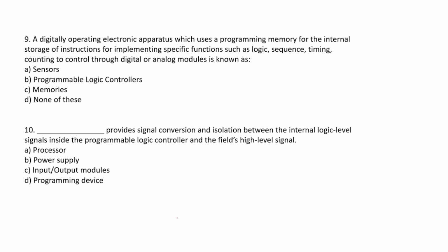In an electric joint drive system, it uses electrical motors to actuate individual joints. In hydraulic, it uses hydraulic pistons and rotary vane actuators. In pneumatic, it is limited to smaller robots and simple material transfer applications. So those are the overview of joint drive systems.